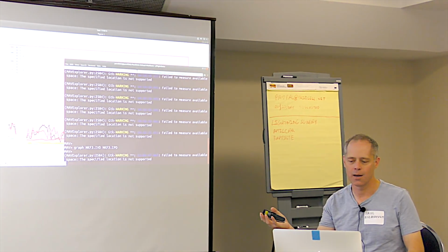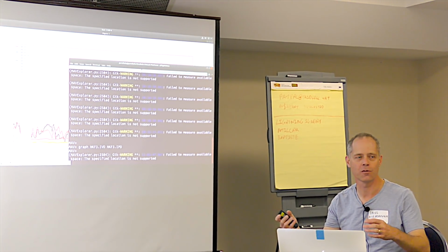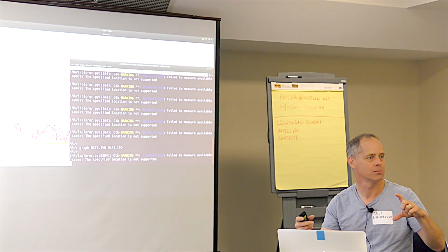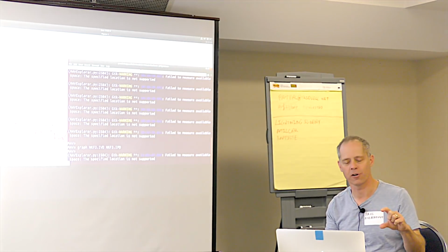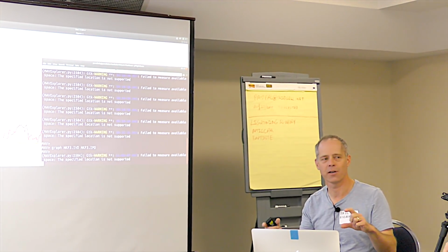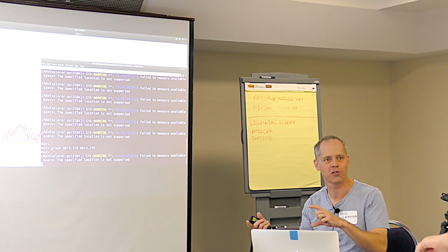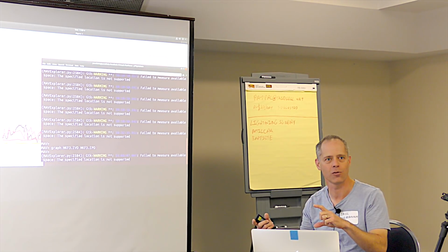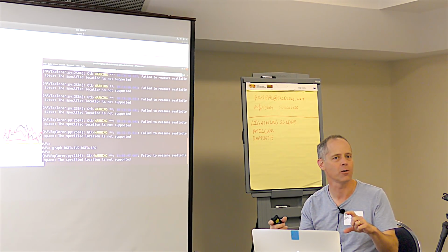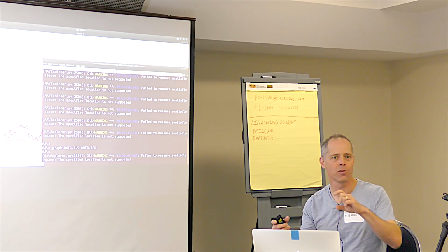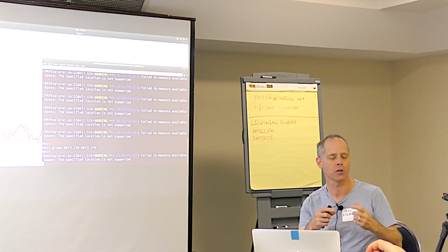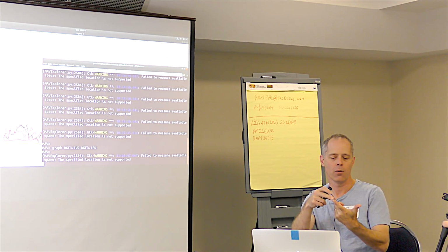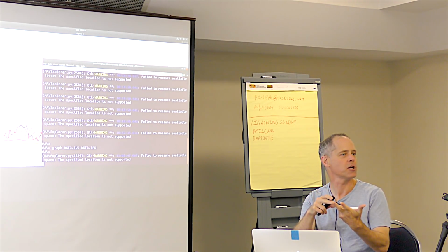Because if the GPS glitches, the vertical velocity will glitch. And in fact, it will glitch more than the horizontal velocity. And the great thing about vertical velocity is that we've got another source that tells us whether it's just vertical velocity in the GPS or if it's something to do with the IMU. And that is, we've got baro. Because we have three sources that give us a measurement of vertical velocity, of vertical motion. We have an IMU, we have a barometer, and we have a GPS.